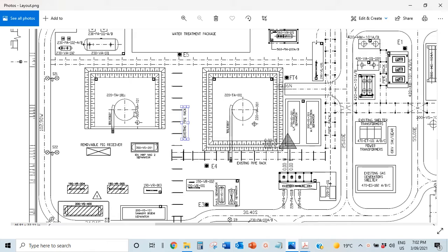So let's say, I'm just assuming, this gets its feed from here. You want to make sure this is closed, and this is on fire. If this is on fire, you want to make sure that whatever is bringing fuel in is closed so that this does not get any more fuel to keep on burning. After a while, the fuel will burn out, because your fire and gas system, your sprinklers, your monitors that spray water everywhere, they don't actually put out the fire.